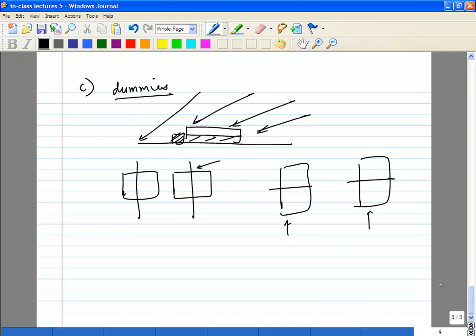So you will have some gradient, and this kind of thing will prevent that. Obviously you can also draw it like this. I just drew it sideways, but you can draw it like this, placing one below the other. But remember, if it comes from this direction, you'll have much less shadowing because the gate is longitudinal. So what you want to do is make sure the gates are in the same direction. That's what I mean.